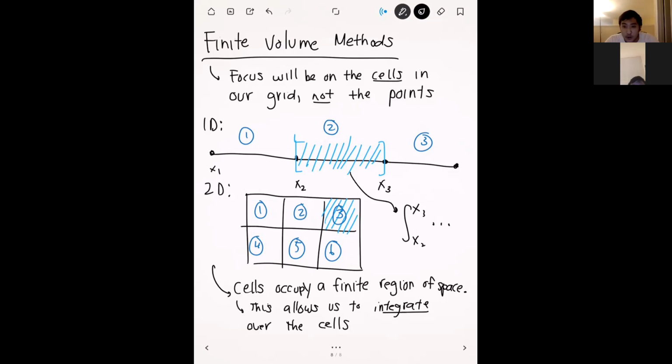All right, question. So are the nodes still used as BC? So they won't be. Actually, in 1D, they will be. In 1D, we just have nodes there, and so the nodes will be a boundary condition there. But for 2D, we're instead going to be applying boundary conditions on these edges. And so our boundary condition is going to be a little bit different than it was before, with the finite volumes. But we'll walk through it step by step this whole time.